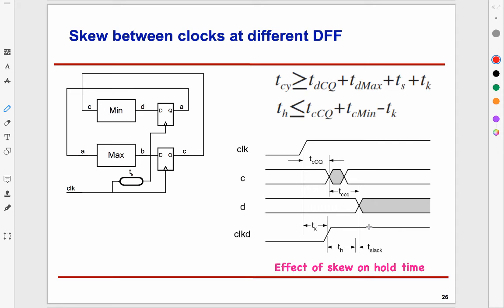Furthermore, clocks themselves, the clock sources, are not perfect. When you observe a quartz crystal oscillator, the edges jitter. What I mean by that is, if I have, let's say, a gigahertz clock, then you would think edges are 1 nanosecond apart, but that's not always perfectly so. One clock edge may come a little bit earlier, the next may come a little bit later, so the clock edges jitter a little bit. That happens because there are fluctuations in voltage, temperature changes, and all sorts of weird physical things. So the net result is that you cannot say that clock edges are observed by flip-flops simultaneously.